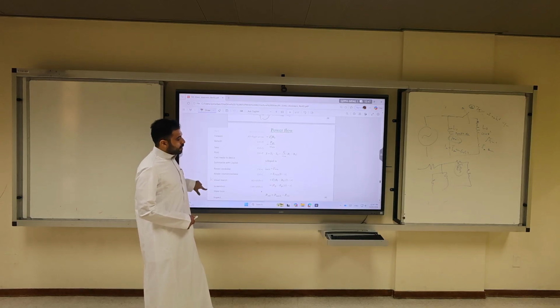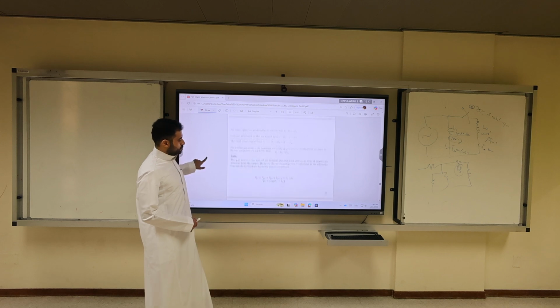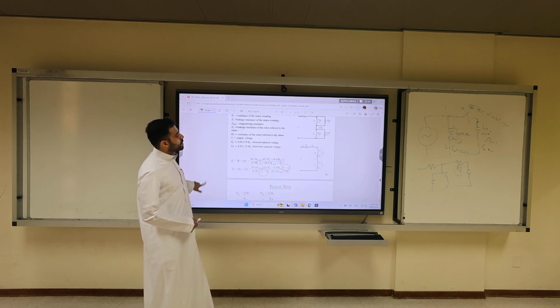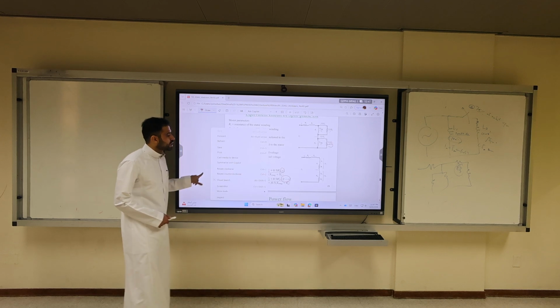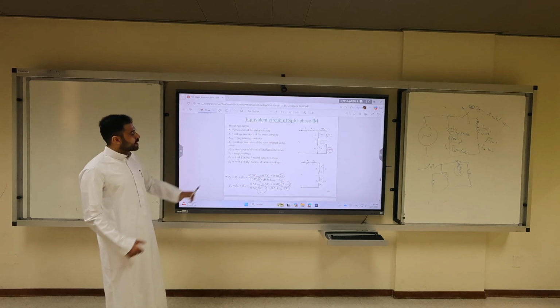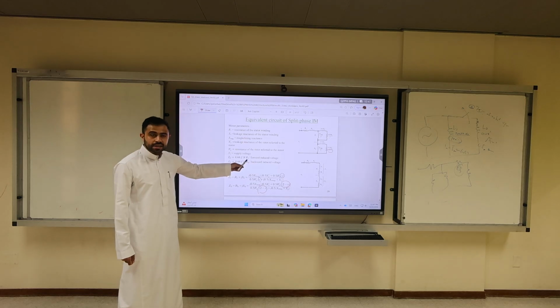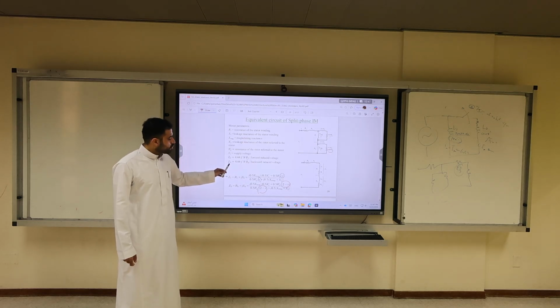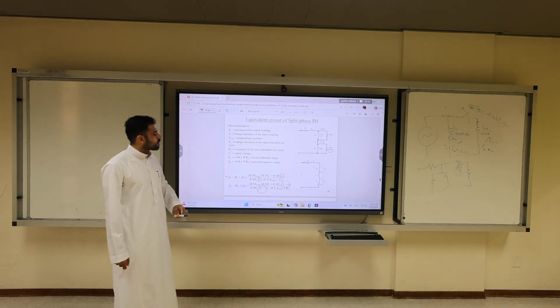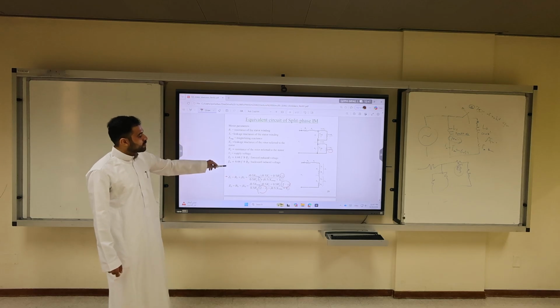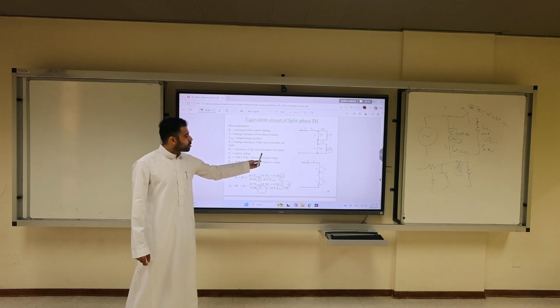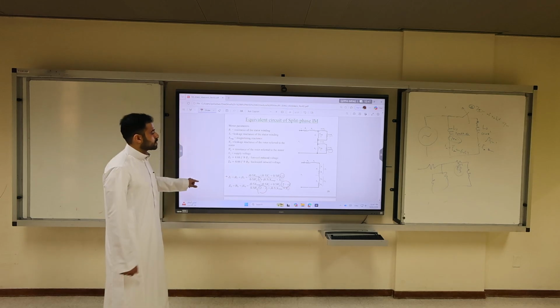What is the power flow? What is the power? Okay, any question about the equivalent circuit? Keep in mind that the forward induced voltage is a function of the forward flux, and the backward is a function of the backward flux. Everything else is pretty much similar. You have R2, for example, the resistance of the rotor referred to the stator, etc.